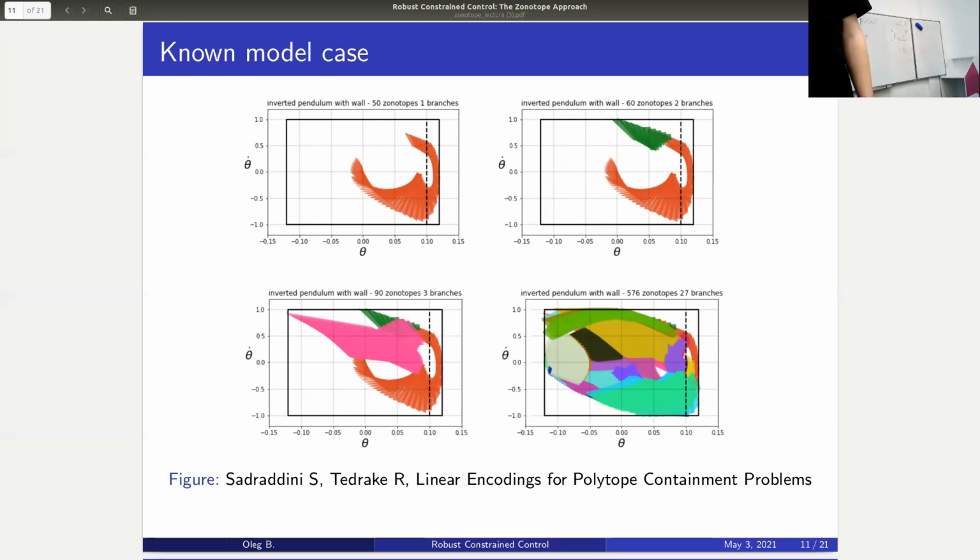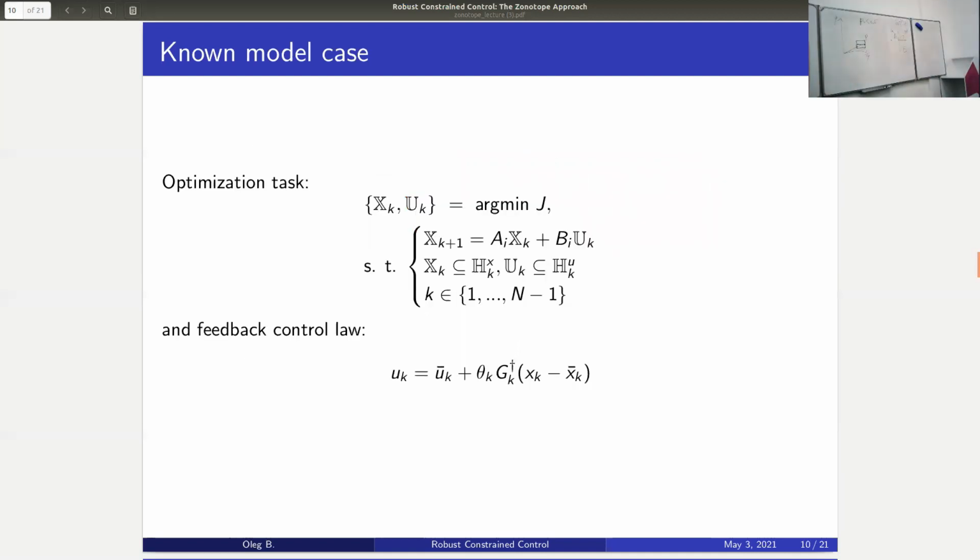So is the U the control input or the feedback input? U is the control input for the generator in feed-forward form. After this optimization, we can find feed-forward gains in the form of multiplication between delta k and the inverse of gk.